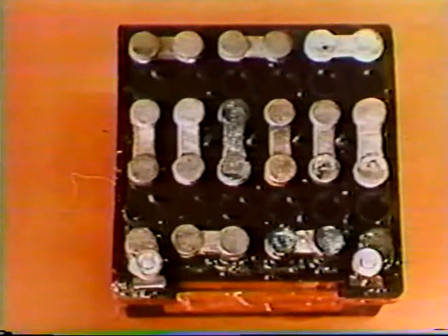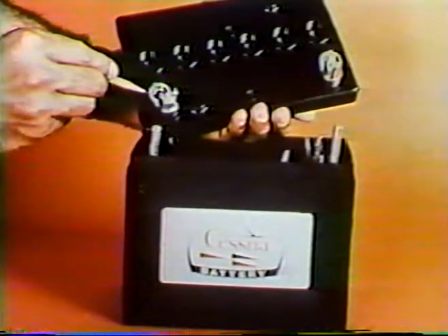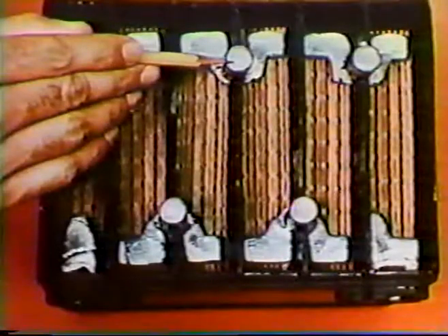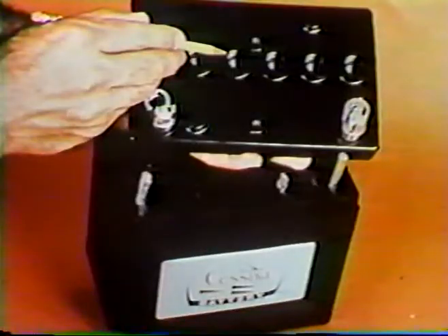In many older style batteries, cell posts stick up through individual cell covers and are sealed to the cell with a tar-like compound. Connector straps connect the cells together. Newer style batteries have a one-piece cover with only the negative and positive terminals protruding. The cells are connected through partitions below the cell cover. Venting and servicing is provided by an opening in each cell.